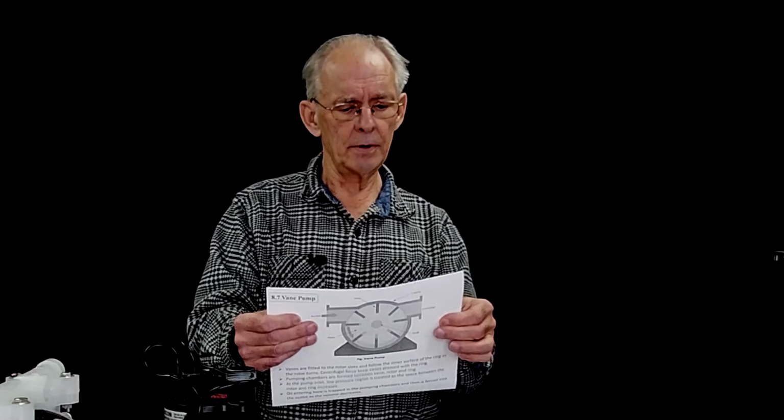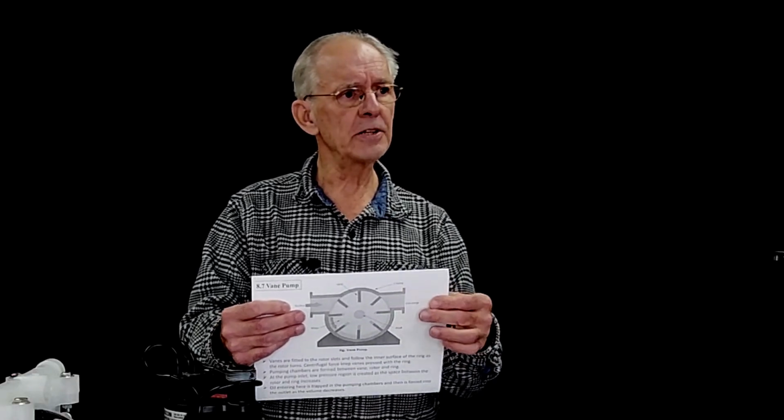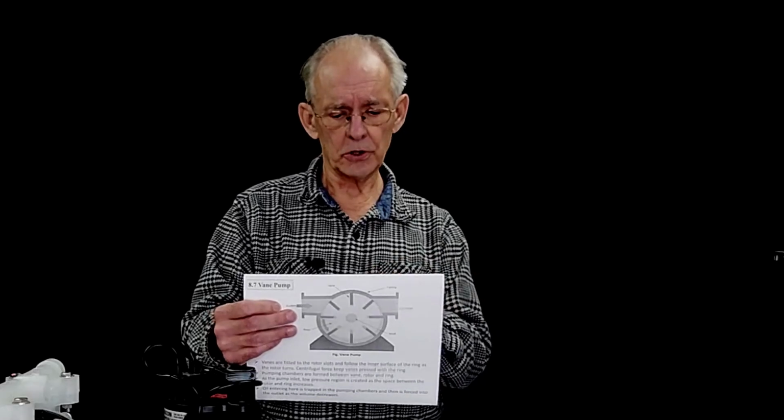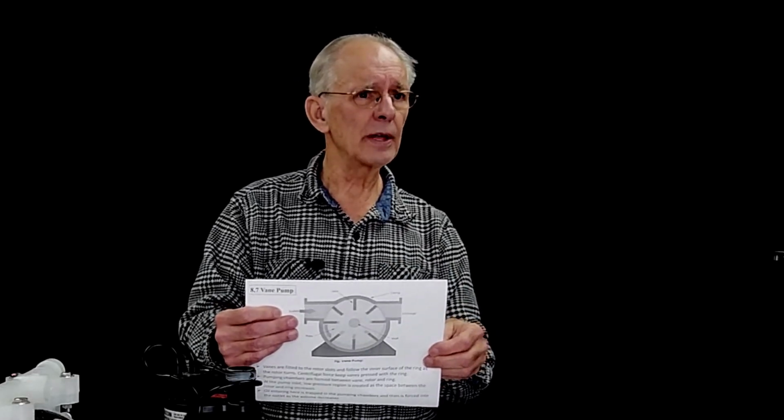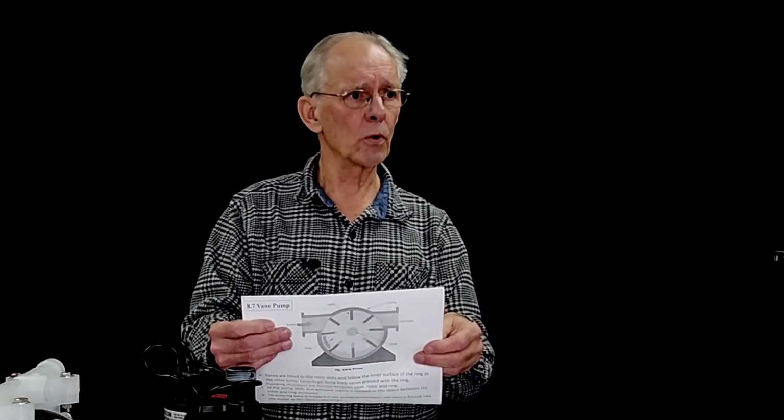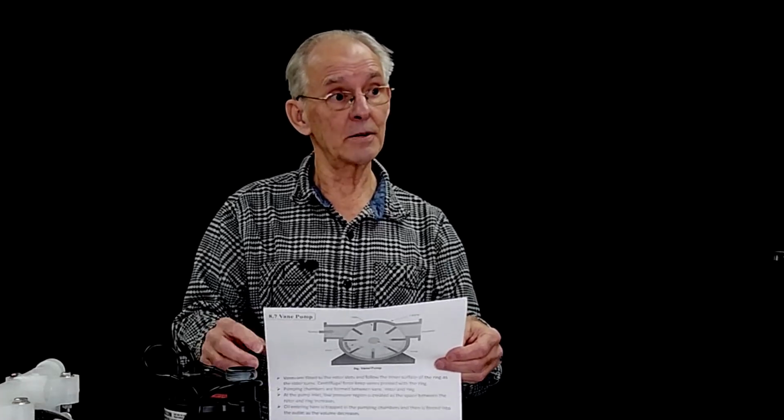Normally, they do not, because the vanes in most of these pumps are actually tilted and not shown straight as you see here, and so they don't like to be reversed. They don't work as well. They will, but they're not really intended to. Then we have gear pumps, okay?